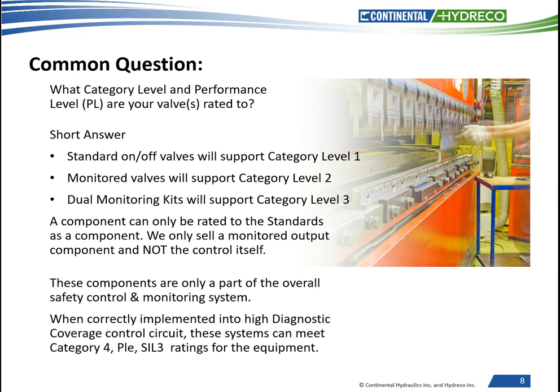The most commonly asked question is, what is the category your valves are rated to? Which actually is a good question, because they are asking what the valve is rated to. An individual component can only be rated to these standards as a component, as they are not the full safety control system. As per the ISO ratings, a standard valve, when designed correctly, will meet and support Category B and Category 1.